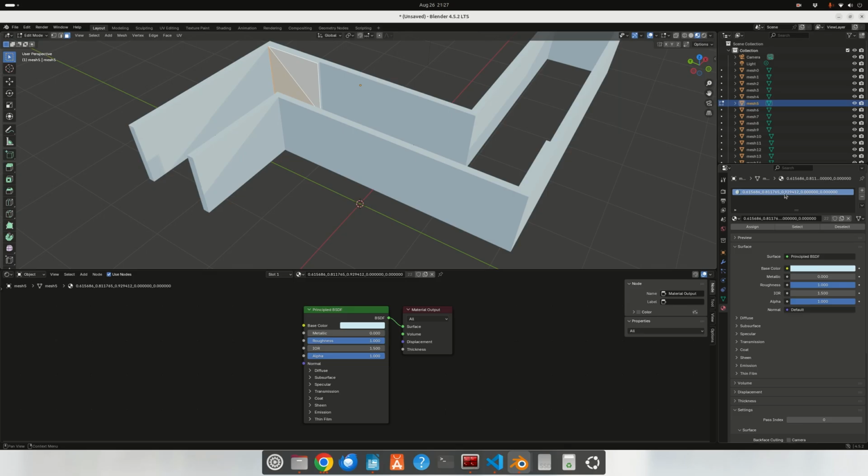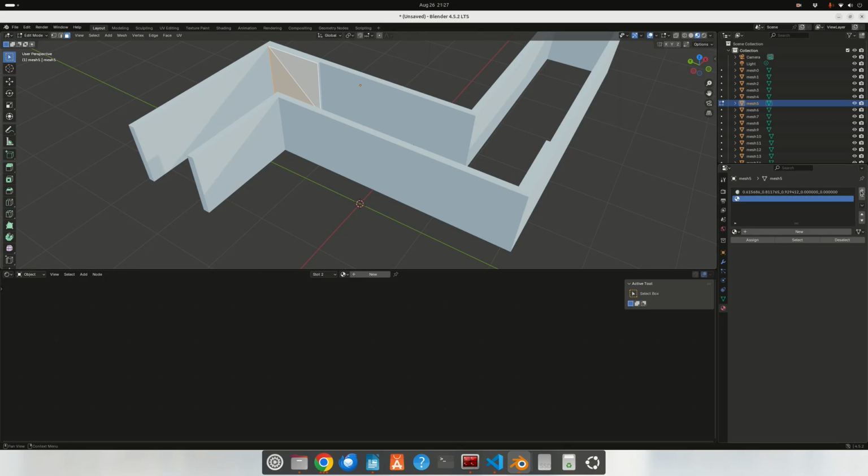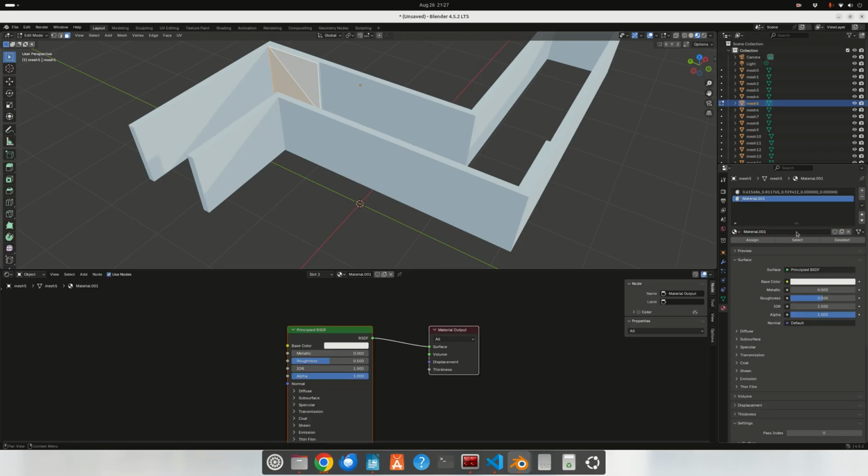And then up here you can see we've got the material for the actual solid shape, but I'm going to add a material slot here, and then down here I'm going to click new, and you can see it's just material.001. I'll call this QR right, and then I'm going to hit assign, and that's going to assign that material to those two faces, but ultimately what is the one face.